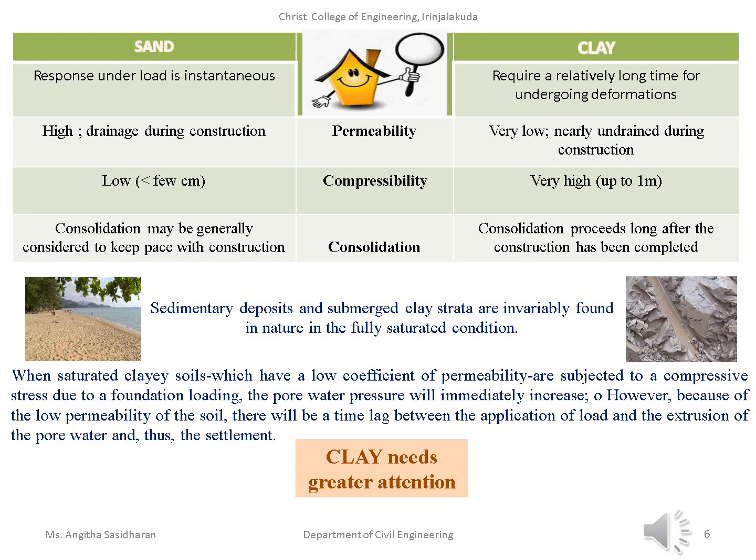Sand and clay is shown here, and the sedimentary deposits and submerged clay strata are found in nature in the fully saturated condition. So the clay strata will be more subjected to consolidation over a long time. When saturated clay soil with a low permeability is subjected to a compressive stress, the pore water pressure will immediately increase.